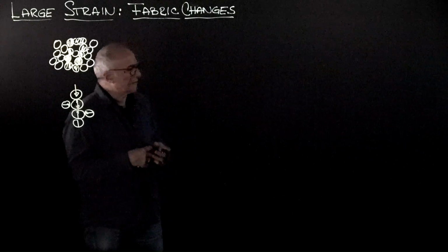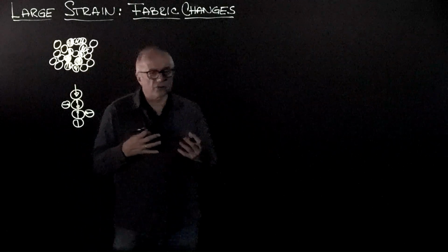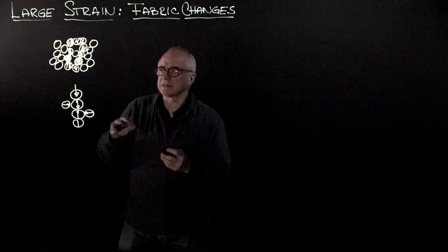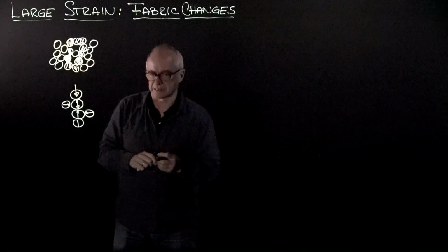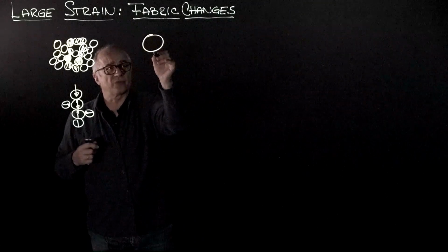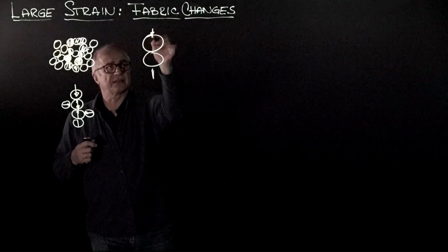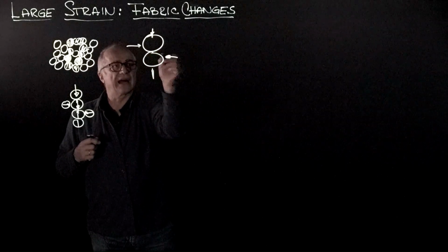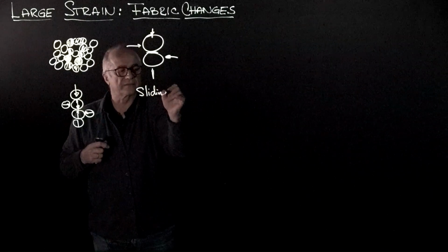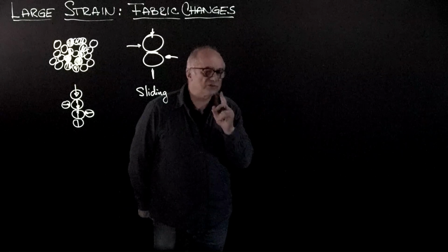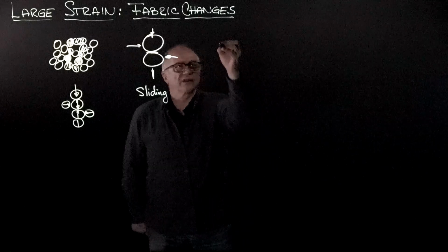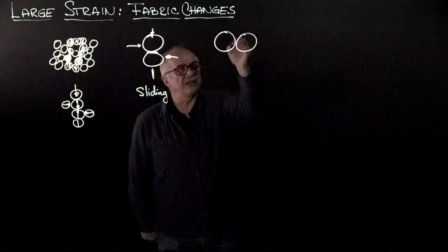Another important observation that we gain from understanding granular materials at the particle scale is to understand the deformation mechanisms. So, for example, one could be that one particle subjected to normal load and shear loads actually slides. So one would be sliding. The other one is rotation, but rotation is tricky because consider the following system of gears.